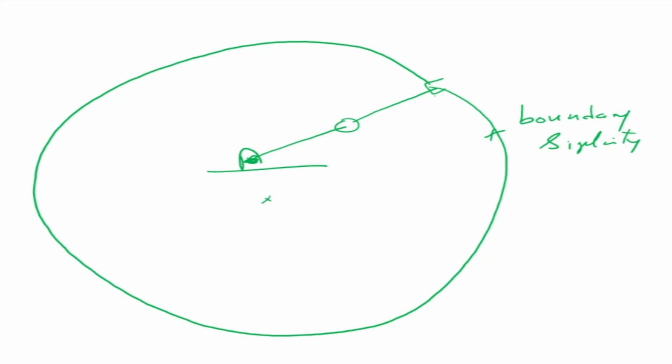Now a 2 degree of freedom planar manipulator does not have an interior singularity. Okay, so all points inside are reachable. But some robots can have a singularity where you cannot reach inside also. Okay, so that gives us an interesting perspective on singularity and how singularity comes on the boundary of a 2 degree of freedom manipulator.